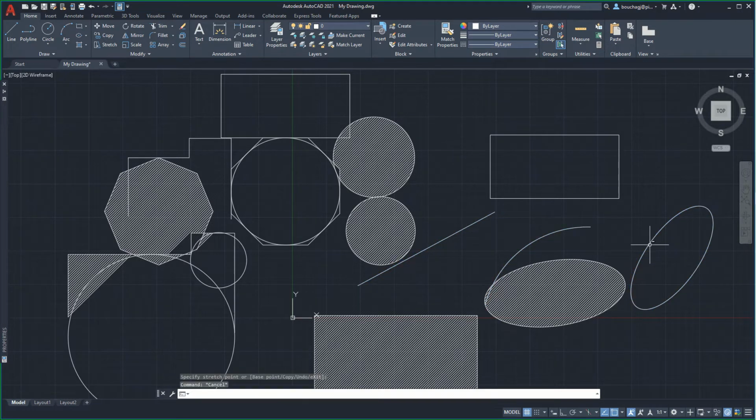When the Stretch command is entered either by selecting the icon or typing S and Enter in the command line, it is used to stretch objects by dragging multiple snap points from one location to another. To selectively stretch, in other words, elongate or shorten geometry, the use of the green back pick box or selection window is very effective.